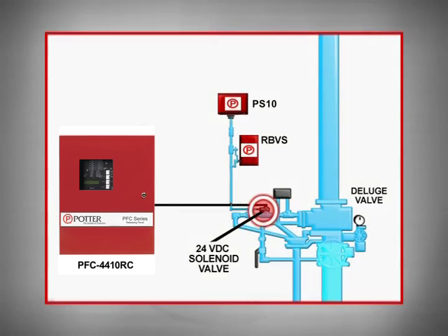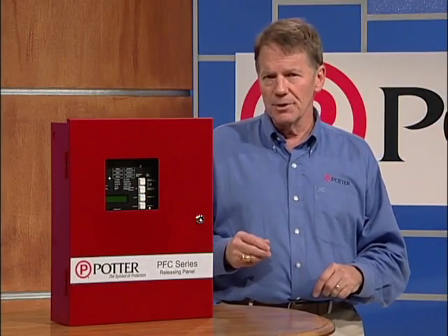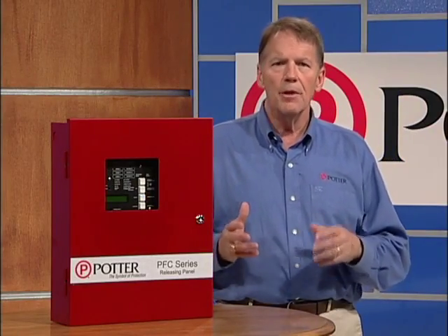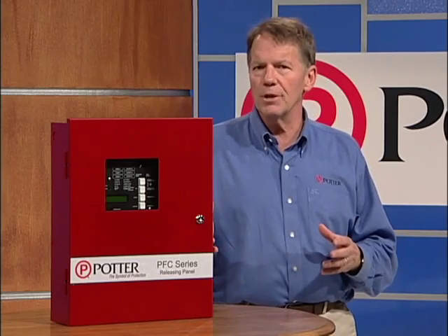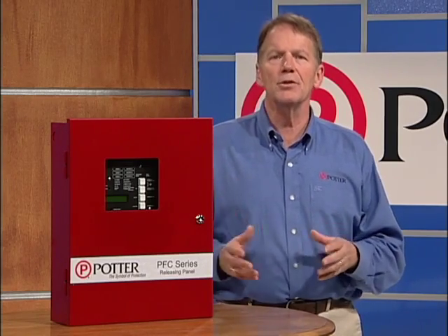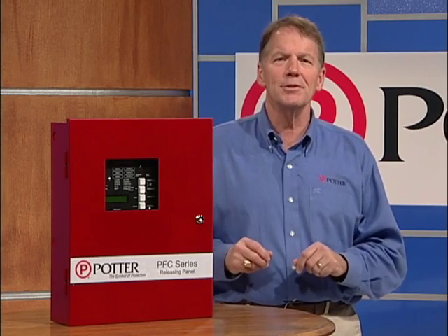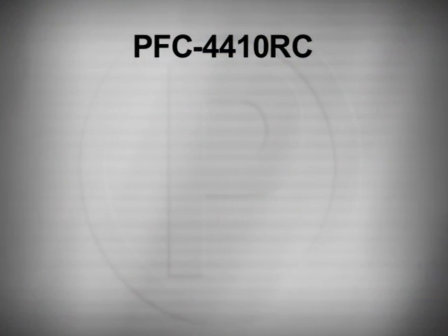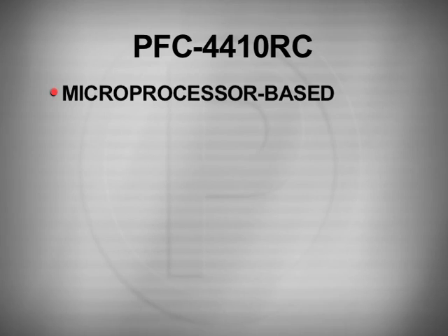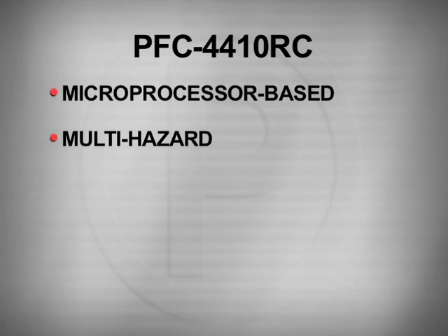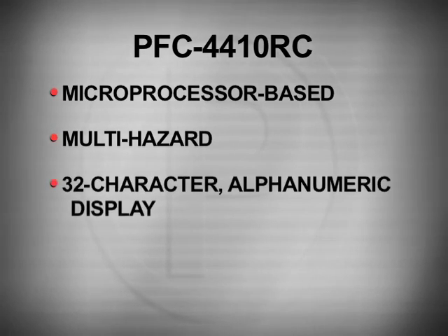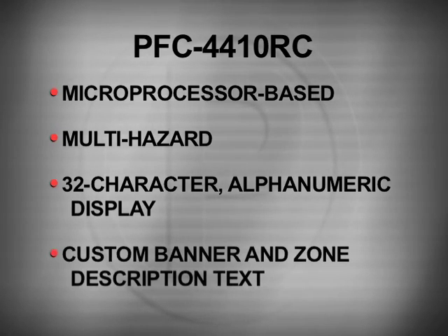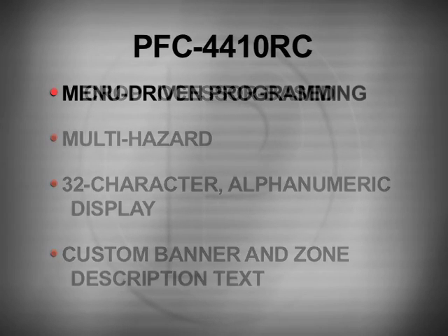For pre-action sprinkler systems and deluge systems, the Potter PFC 4410RC releasing control panel is the panel of choice. The PFC 4410RC is a microprocessor-based multi-hazard releasing control panel. Allowing for maximum flexibility, the PFC 4410RC features a 32-character alphanumeric LCD display, custom banner and zone description text, menu-driven